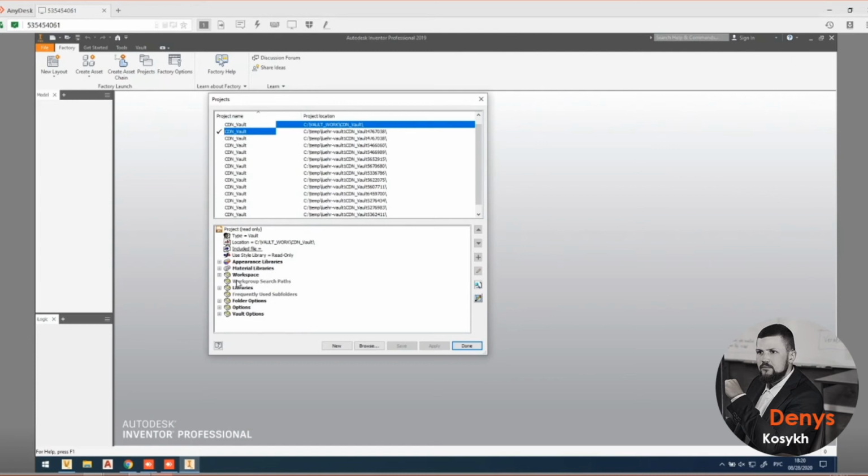If you just open Inventor, you can see here projects, and you can create an IPJ file with a lot of paths, so that for a project like GFE solutions, you will have libraries, and you say that the library should be positioned on some server maybe.